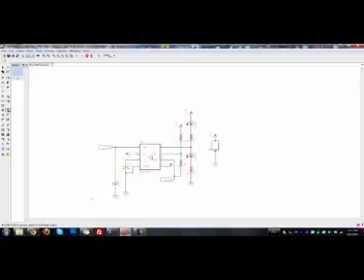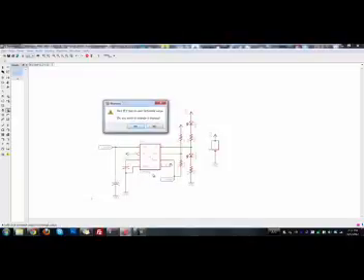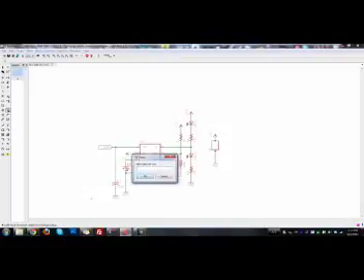And that's important. You'll notice that the 555 timer doesn't have a user changeable value. It's already set to LM555D. So we don't want to change that. That's fine. But we do want to set the capacitor values. So C1 is 22 microfarads. And C2 is 0.01 microfarads. So we'll define both those things so that we can make sure we order the right part and whatnot.